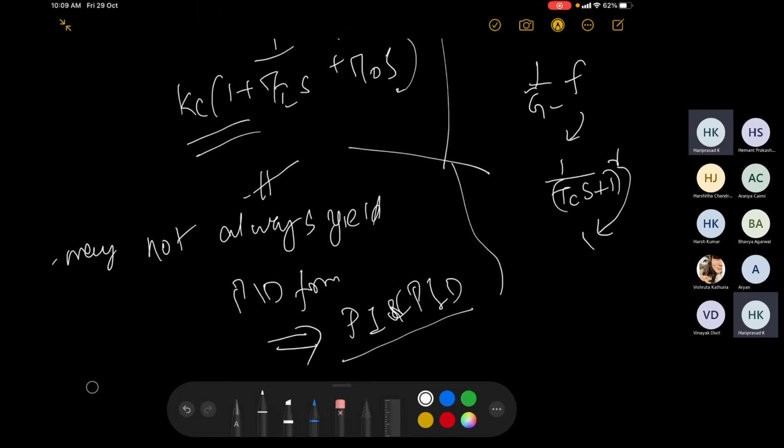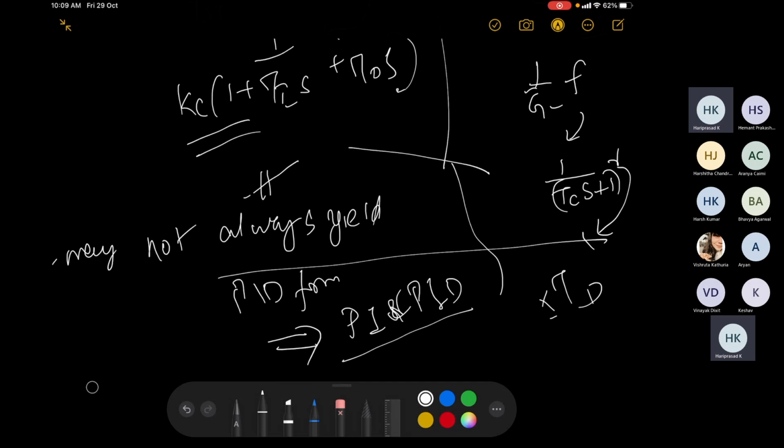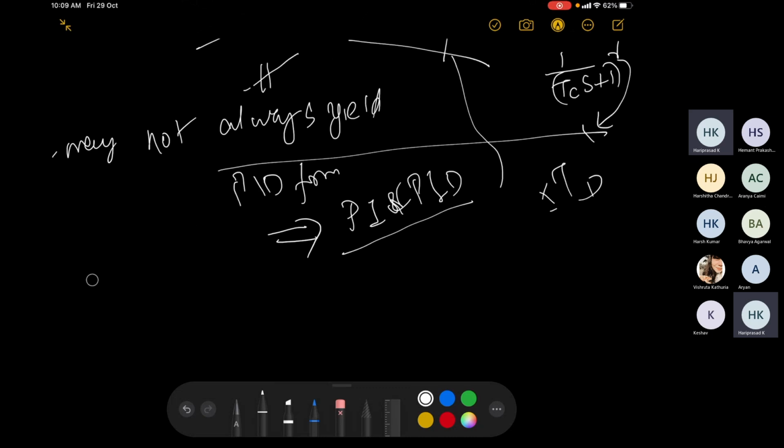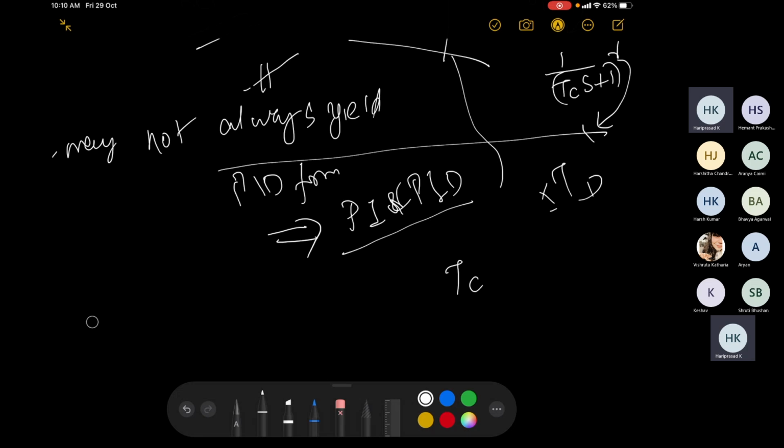Okay, so the same thing kind of applies to IMC also. When you do this filter-based analysis, you might see that sometimes tau d, most likely, would be the absent term. Because of the first order system, you would not be able to figure out what is the coefficient of s. So this is not a lacuna. I'm saying with PID, you might not eventually get a D term there, but you surely happen to get P and I.